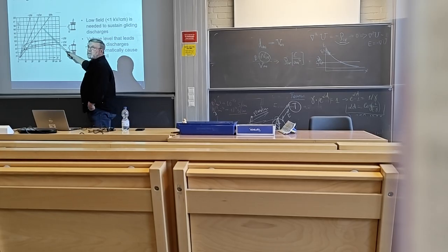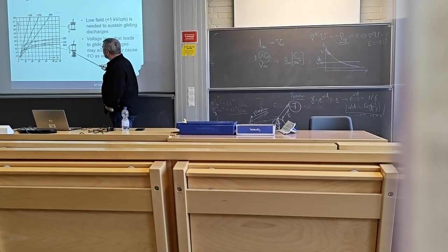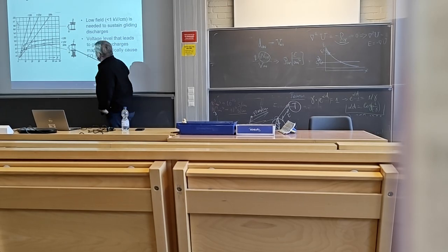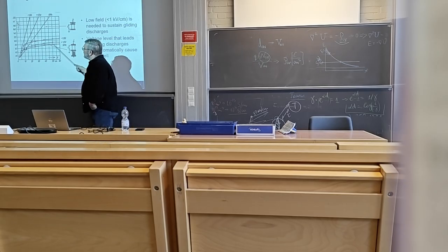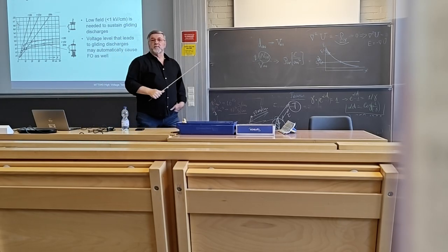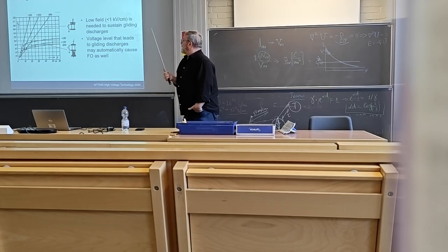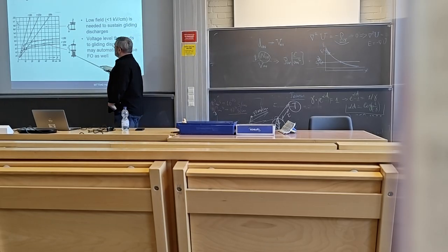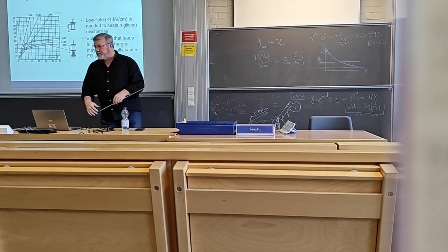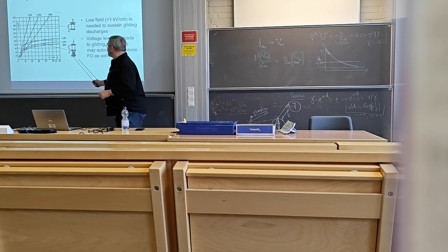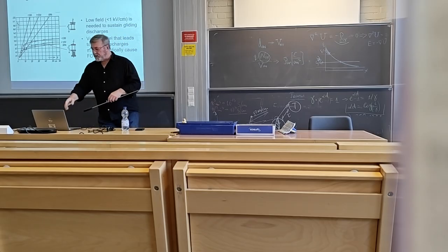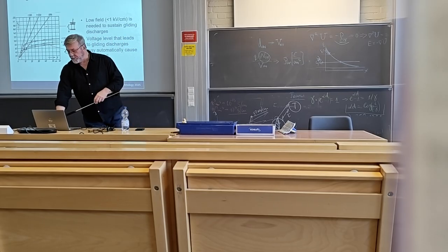So it's a completely different story, because there is a normal component of the field now created, and instead of having the breakdown through air, like here, you initiate actually the creeping discharge, which needs much lower voltage to propagate. So that's why for bushings, this is really a critical situation. One needs to always consider both tangential and normal components of the field.